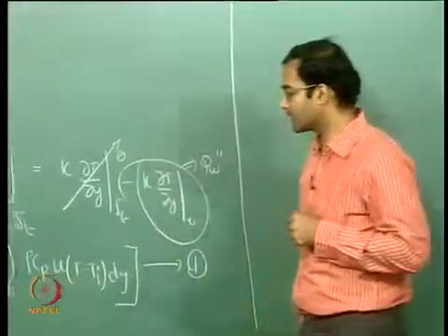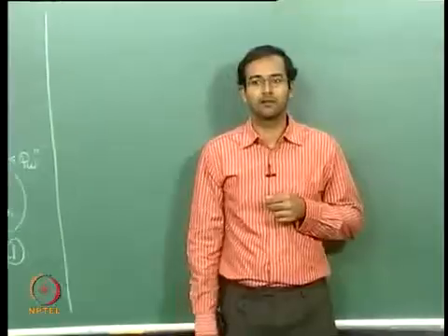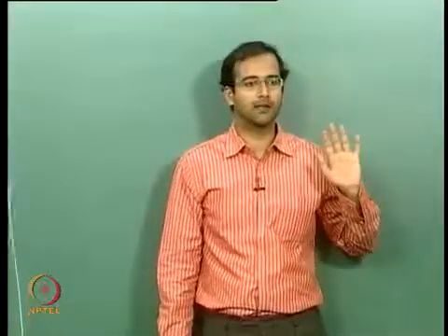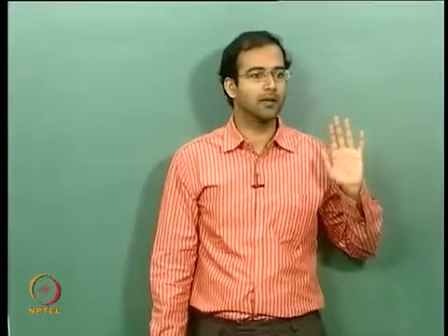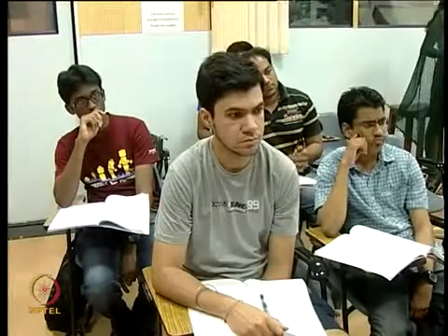As far as the velocity profile is concerned, we are not going to solve the momentum integral because it is now hydrodynamically fully developed. Therefore we cannot guess any velocity profile, but we have to take the exact profile as it is, okay, because if we had guessed a profile and applied the momentum integral, that would be valid only in region 1, and that too in the developing section.